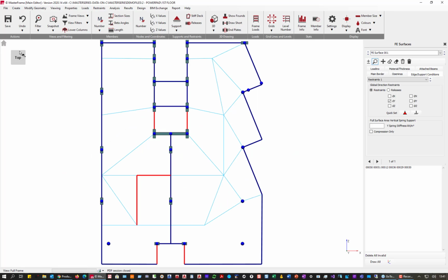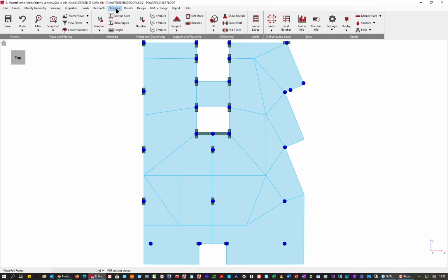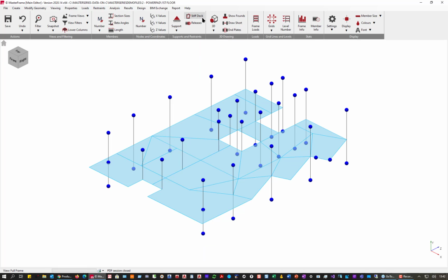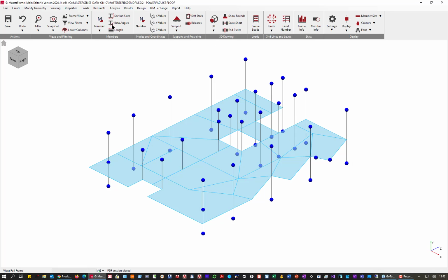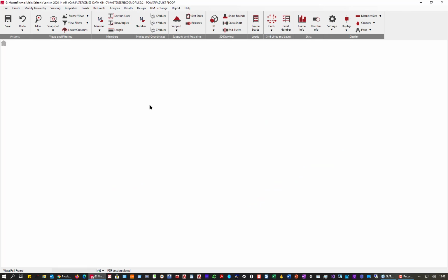So if I put this in the top view, we can see that wall there, a wall there, and 2 walls back there, because you don't have columns underneath. We don't have columns underneath here and here. So we're going to have big problems around here, and we've nice wee cantilevers and everything. So all very straightforward, except the guy did load it up quite heavily with point loads in different places and line loads and the likes. So I'm just going to go straight into my results and graphical.